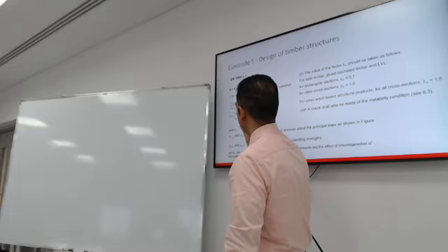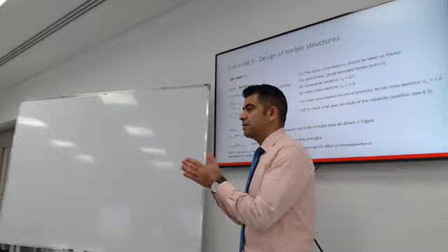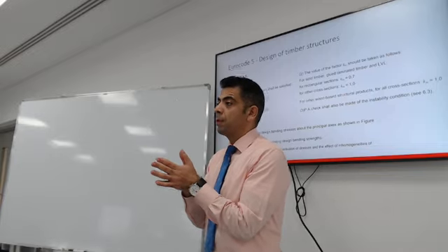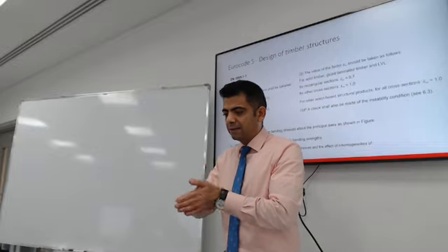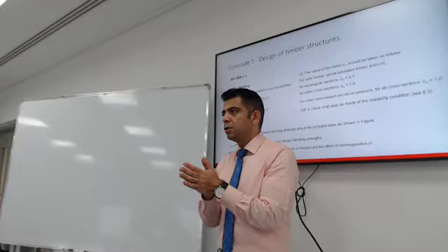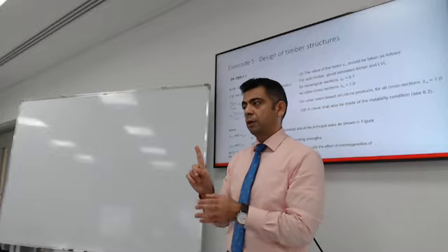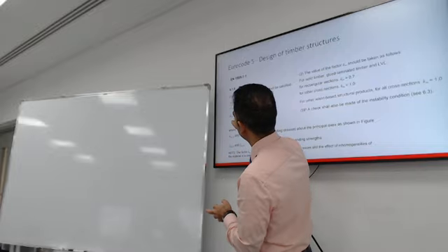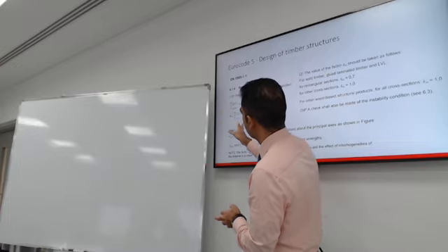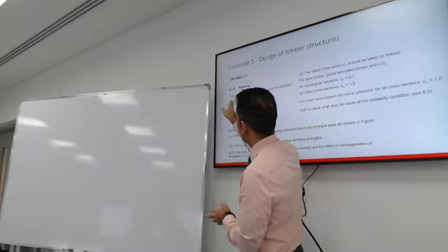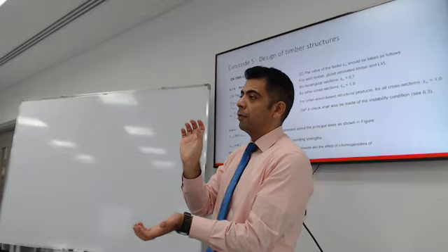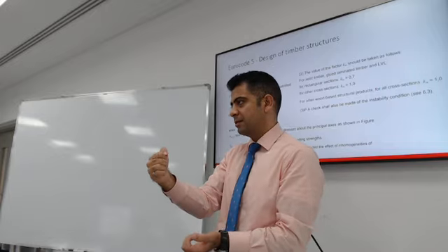All right, so this is the equation for bending. In order to have a section strong enough to resist the loads on it, it could be exposed to bending about the strong axis and the weak axis. Most of the time, you have bending about one axis only. So if that was the case, you look into the formulas, and the top part is the stress due to the applied moment, either about the y-axis or about the z-axis.